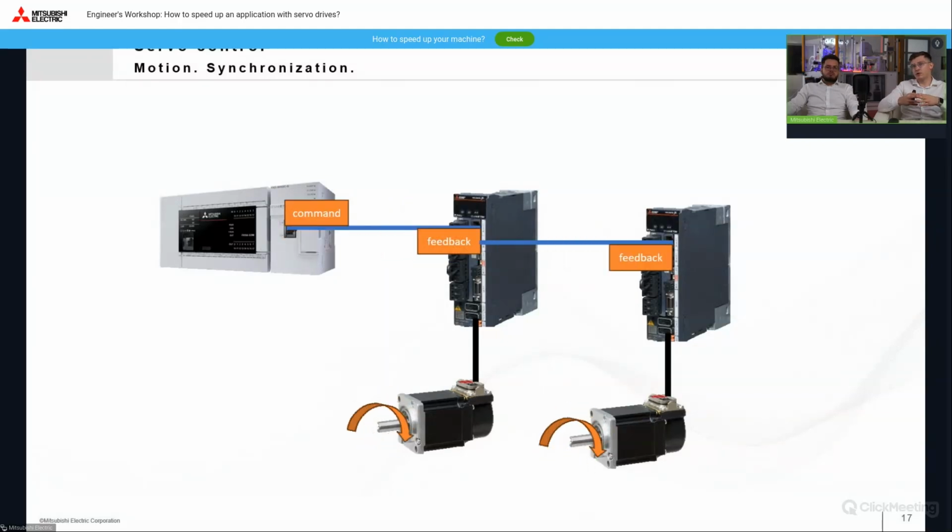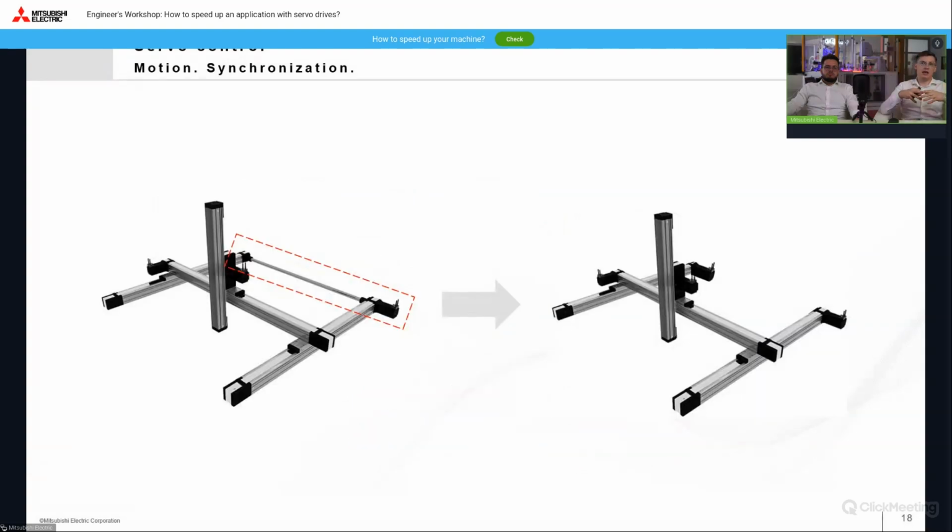This solution is used, for example, in a tandem axis. Typically, a mechanical solution is used in this case. We connect both linear axes via a long shaft, but this is not always the optimum solution, especially for large moving masses. We lose precision and risk skewing the drive element. In addition, this significantly increases the moment of inertia reduced on the motor shaft.